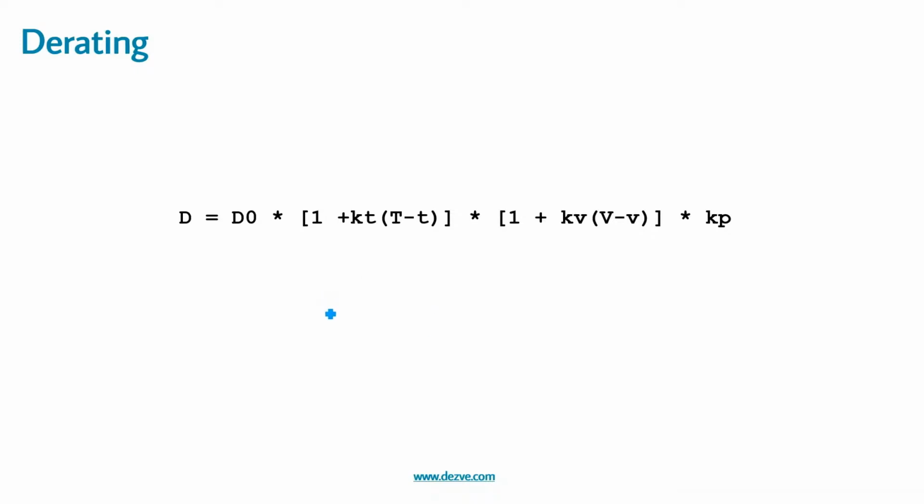Now there can be process, voltage, temperature (PVT) derate values also specified. Suppose we characterize a library at 125 degrees centigrade, and then for a smaller variation, like 120 degrees centigrade, they would have run a similar set using 120 degrees centigrade and then computed a scaling factor. That scaling factor is basically the derate for this temperature. Similarly, it can be done for process and voltage, for slight variations.